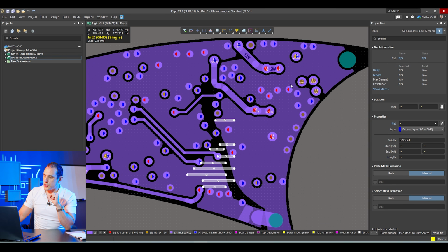Now even though this return current path passes over a lot of solid copper on the top side and the bottom side, the problem is that the return current loop that you trace out around this board is huge, and that gives it a lot of opportunity to radiate noise. Even if the edge rate isn't very high, this could create a radiated emissions problem that also causes you to fail radiated EMI testing. Now, of course, it's possible that these lines are just carrying DC current, or maybe they're low-speed digital, and you don't have any problems with radiated emission.